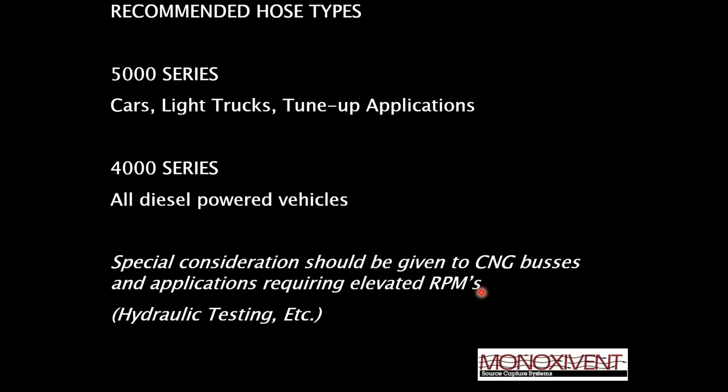The 4000 series hose, again, has a great bending radius, so it's perfect for overhead systems and hose reels. Now, this is for higher temperatures, so this will do 600 degrees Fahrenheit continuous and up to 1250 degrees intermittent.